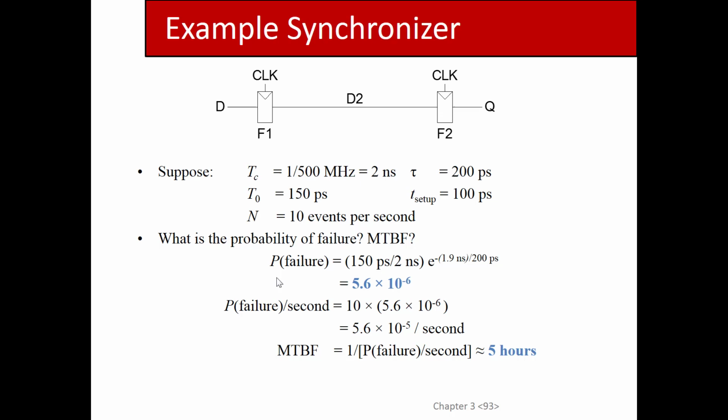What I was saying was, if D2 goes into metastability and that metastable value reaches F2 within F2's hold time, then couldn't that cause Q to go into metastability? Yes. Okay, but you don't worry about that possibility? Oh, I'm sorry. I see what you're saying. You're worried about the contamination delay of this path. I see. I'm sorry. Yeah. That's a good point.